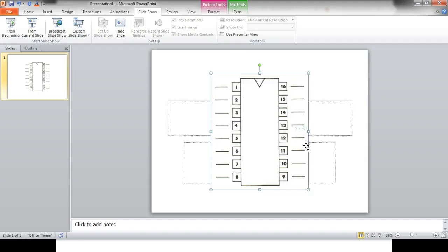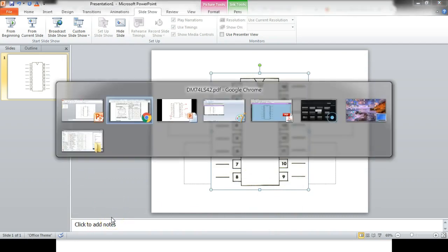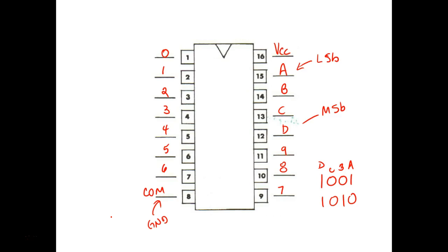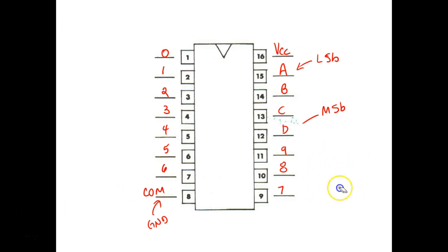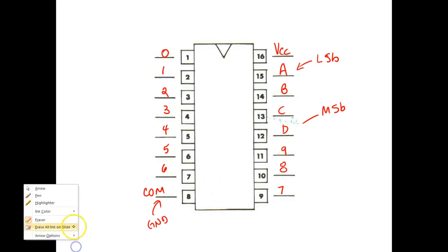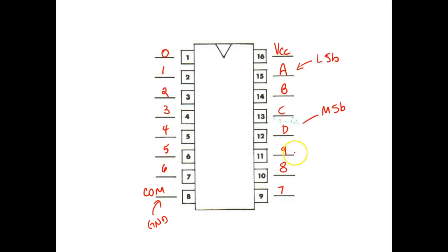Now, since we don't have an output 9 and 10, since all our LEDs go from 0 to 7 on the trainer, what I've done is I've added 2 LEDs outside of this. These are going to come on with lows, so these will operate just slightly different. I've taken this pin and I've put a light emitting diode right here.